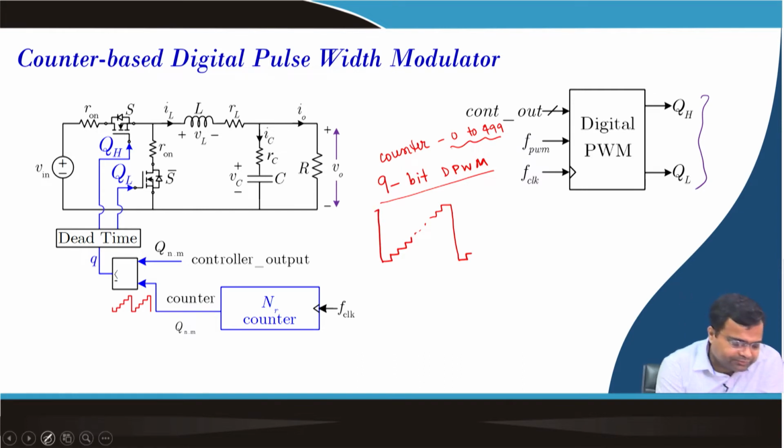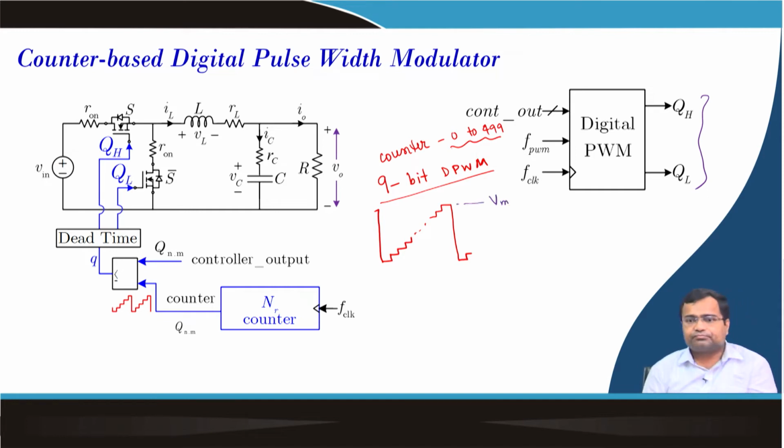Okay. Now, for the counter it is just a number, but in real life this corresponds to some voltage, because if you pass this signal through a D to A converter, it should appear like an analog voltage. So, we want this Vm to be, let us say, 2 volt and this to be 0 volt. Then for the counter it is 0 and it is 499.